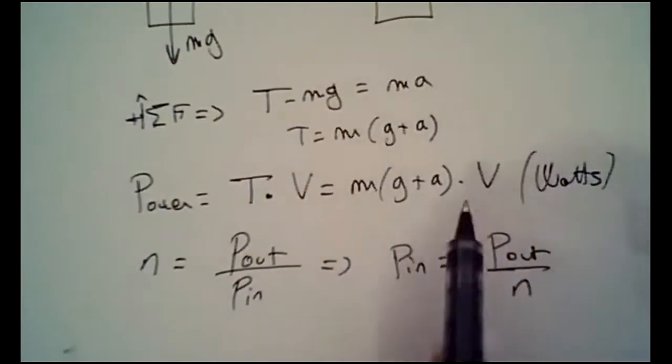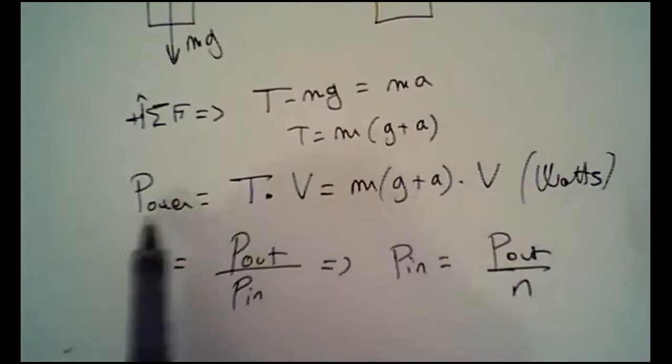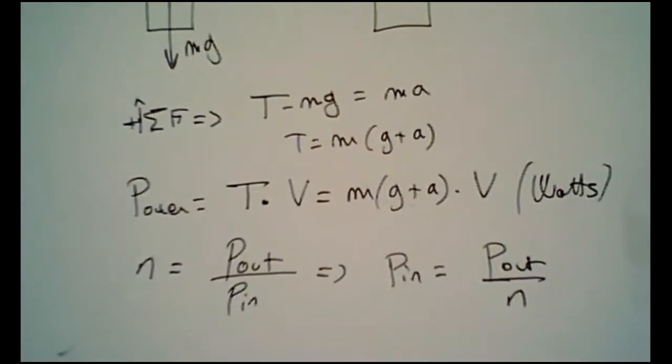So if you have 1,000 watts here, then if you want to look into electrical motors, you can find an electrical motor that has 1,500 watts or 1,200 watts, and you multiply that by the efficiency of the motor, and you want that to still be greater than the maximum power in your system. Okay, guys, so this is what we have here.